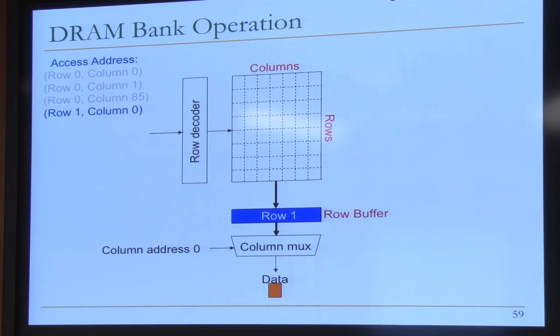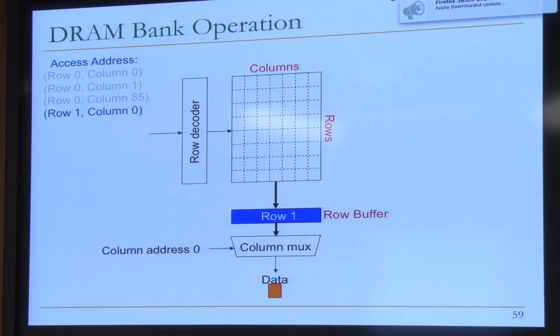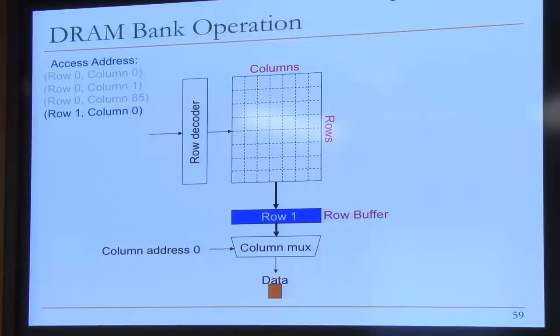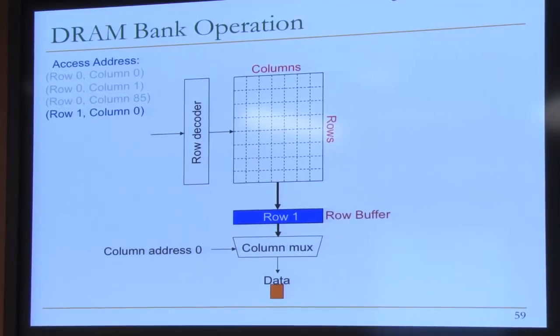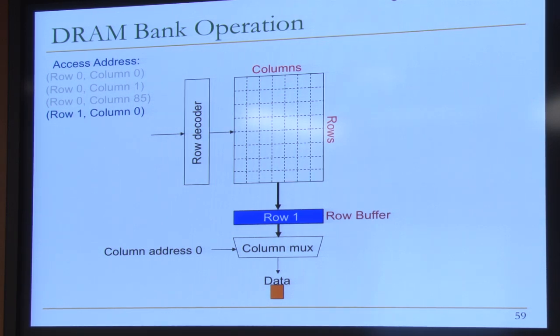Okay? But at the circuit level, what happens is that while the sense amplifier is connected to the cell, they're all at the same voltage level. Right? You're just disconnecting it to change the voltage level of the bit line. Okay? Yes? When you change a value in the row buffer, even before you write it back, it's already changed. Exactly. Yes. Exactly. Yeah. So that's a very good way of thinking of it. Of course, you need to wait until that write takes effect. Right? There's a write latency. It's called the write recovery penalty to ensure that everything gets propagated into the cell. Okay.